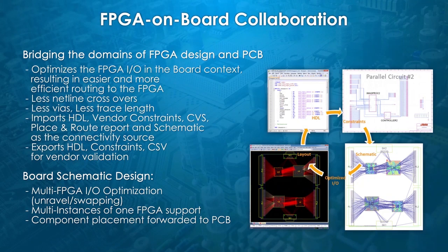With multi-thousand pin devices, and without the appropriate design methodology based on an efficient I/O optimization, but also on an optimal FPGA onboard placement, FPGA onboard integration may lead to unroutable boards, which require best case several time-consuming iterations between the FPGA and the PCB design teams, and worst case a change of the board size or board stack-up, inducing unexpected extra costs.